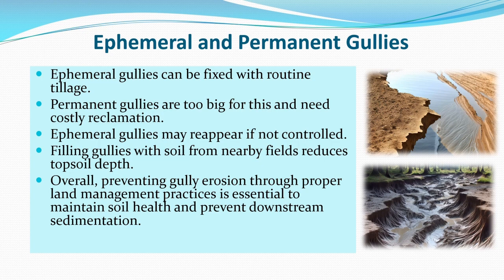So it all started with splash erosion caused by raindrops, then inter-rill erosion, that is thin sheet of water will flow in between the rills. This is called inter-rill erosion. Then water is delivered into small rills. These rills may get enlarged and form gullies.